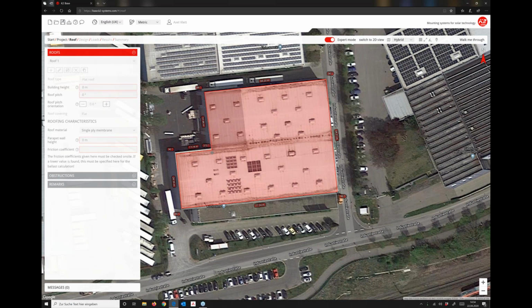When you want to finish this, hold your mouse on the last position, and you see the line on the outside of your drawing field is green. If you are inside of your drawing field, the line is red, and when you're on the last point, the line is green. The green line says you can finish here. If you don't find a point, you can push the control button, and it switches to the green line again. Left click, and finish.